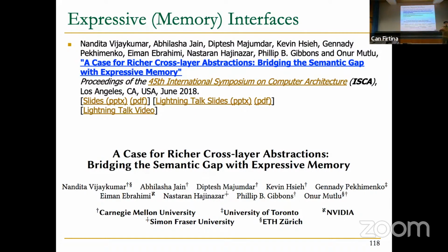You want the processor to access data as quickly as possible, so you want it to always find data in L1, if possible, because otherwise you have to go to DRAM and bring the cache line to the L1, and that will take probably hundreds of cycles of execution, right? So there are specific mechanisms and units in the processor in charge of bringing the data in advance, so that when the processor needs one specific value, the corresponding cache line is already in the L1 cache. Is that always going to work well?